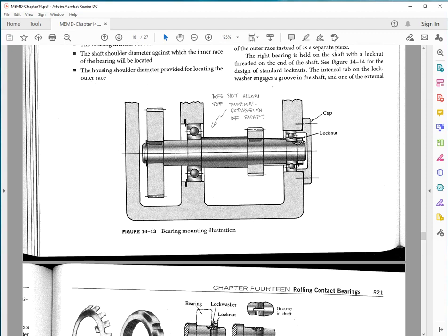Studying existing mechanical drawings is the best way to learn how to design with bearings. Again, make sure you can assemble in a convenient way, and also make sure to allow for thermal expansion. Never consider having 3 bearings on the same shaft. There are some instances where you could.